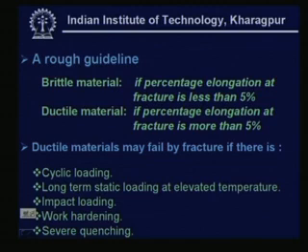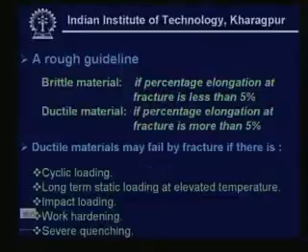Just due to that particular temperature effect, what happens? The simple mild steel which was behaving like a ductile material may just behave like a brittle material and fail. These sorts of incidents occurred in World War II, when the ships from the German side went to the Arctic sites. So, the effect of temperature, combined with impact, is a severe situation where brittle failure behavior can be exhibited in a ductile material too.